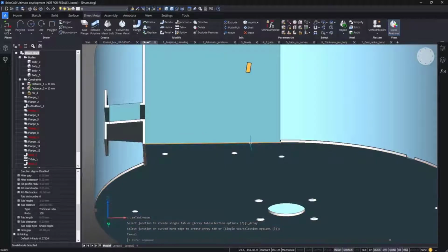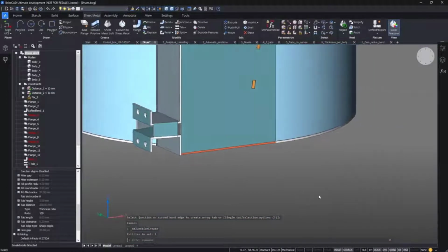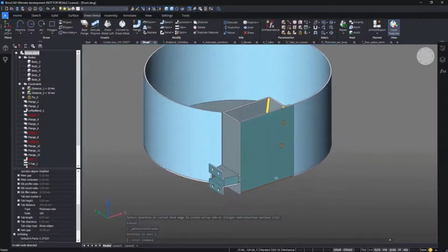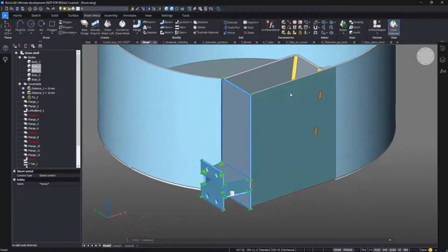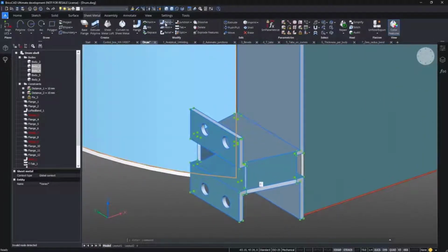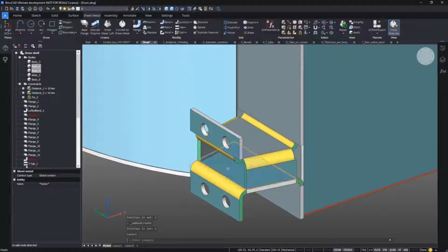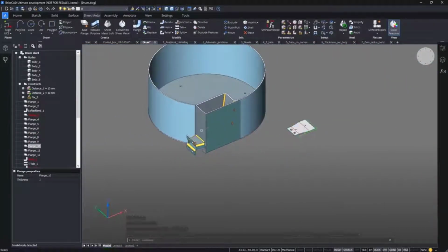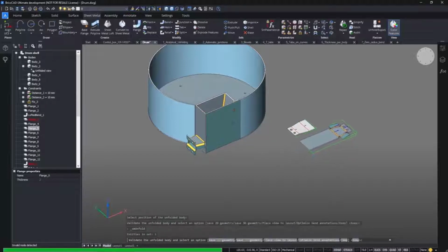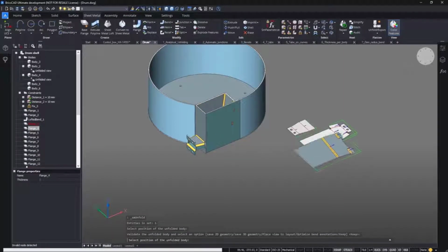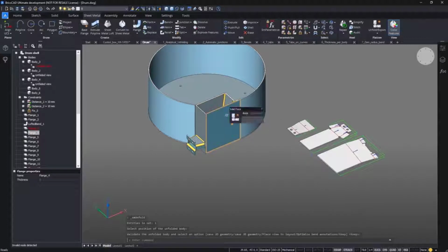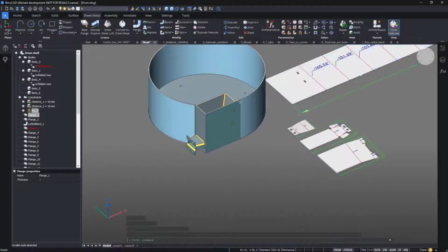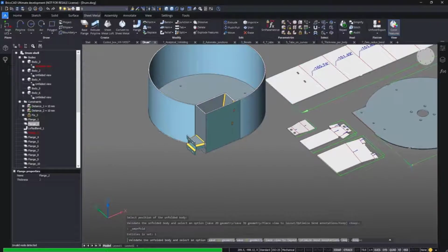Of course, now we must create a junction here to separate the parts. And to finish, just select the remaining part in a rectangle and click on Create Bend. Those solids are fully transformed in unfoldable parts. Finally, we can unfold all the parts. Very impressive.